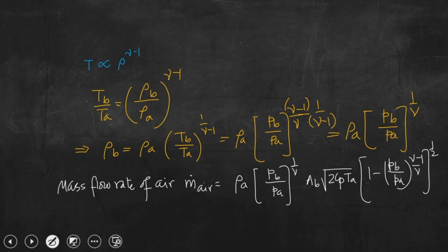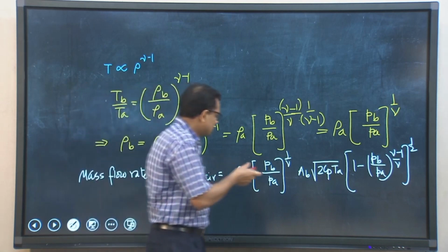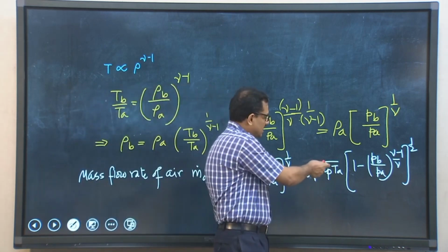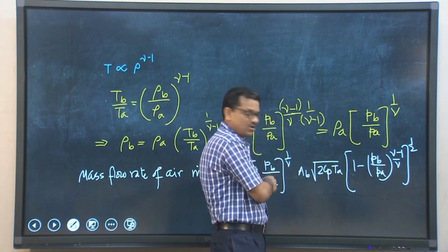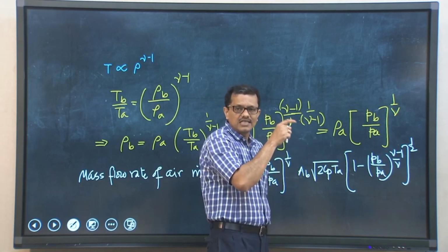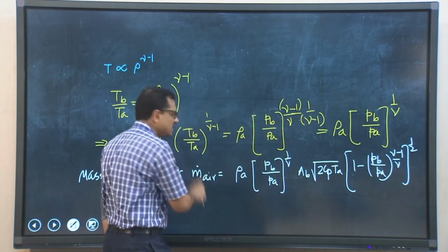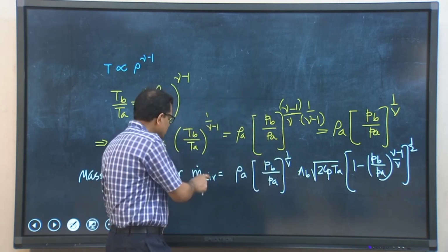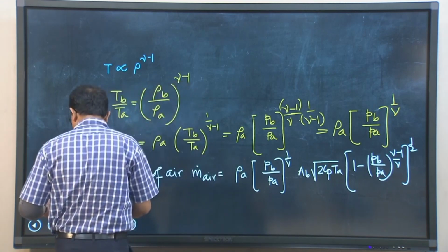So, this is the expression of mass flow rate, that is what we wanted to have, right, because for a given dimension of the venturi, that is Ab, ambient condition we know, because Cp, Ta and Pa are known, we can measure Pb by connecting this U-tube manometer that we had seen in the schematic depiction. We can calculate the mass flow rate of air at section Bb. We can write this expression further in a closed form.